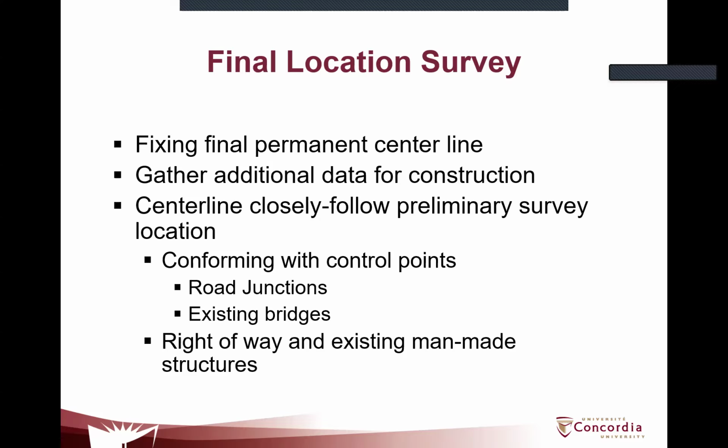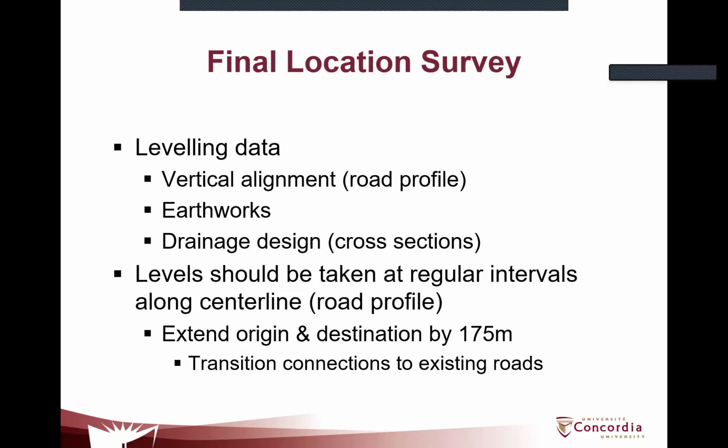Then you also need to look into the junctions with other roads, where you are going to establish what are called control points, and also the existing bridges. And of course, you are going to have to trace along the center line some additional lines which will illustrate the edges of the road and the edges of the right-of-way. So a center line for the location of the road, and then two additional lines for the edges of the road and two additional lines for the right-of-way.